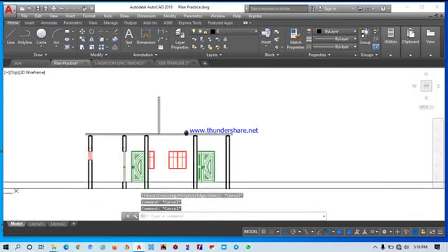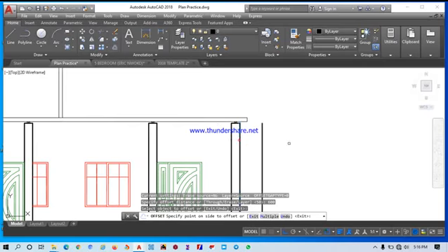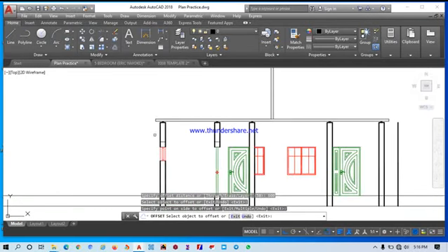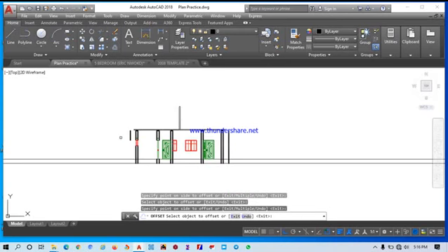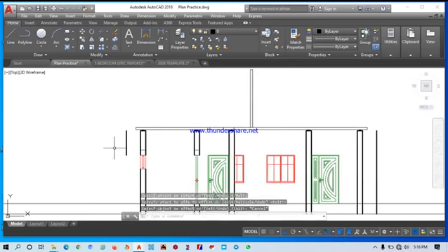So the next thing to do before we proceed, let me offset my eaves. Like I've explained in the previous video, your eaves are that extension, that 600 mm projection from your external wall. It prevents the rain from falling directly on your wall. It serves as a shade also, so that the sun will not just be penetrating directly into your building. Someone can hide under the shade. So let's offset the eaves 600 mm.